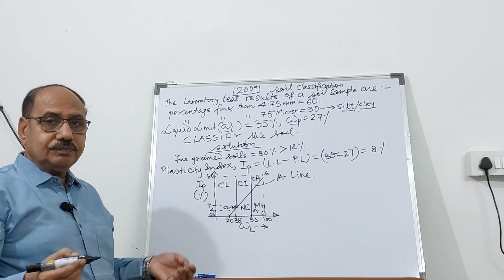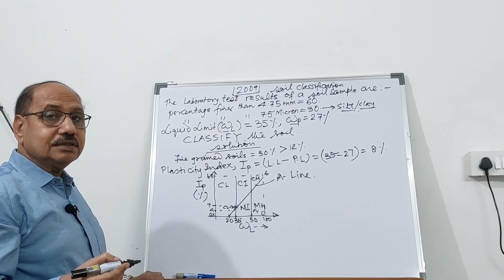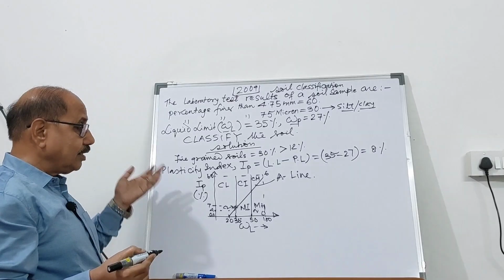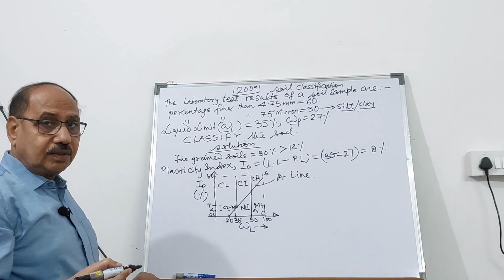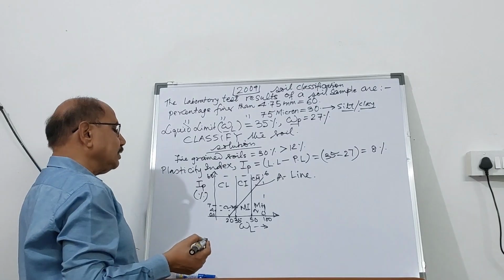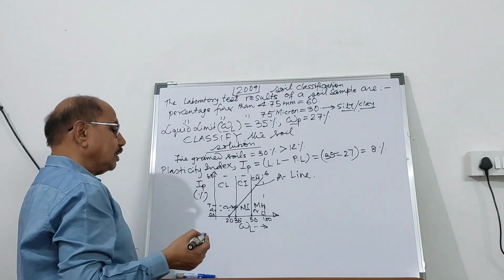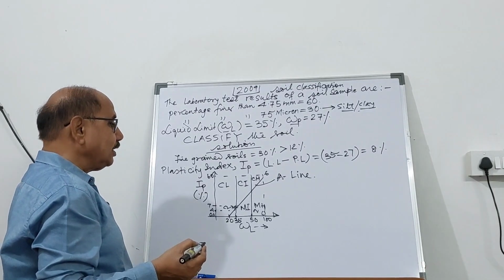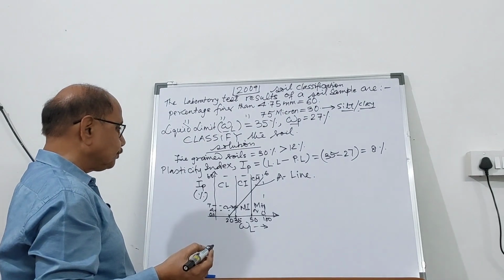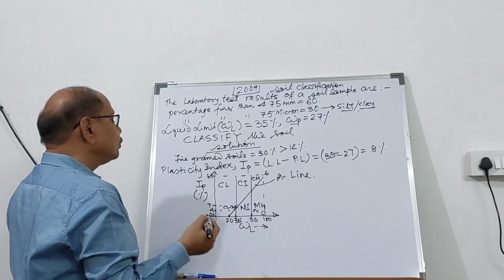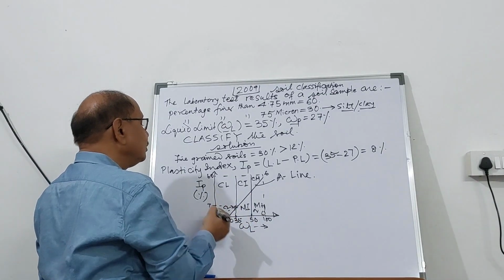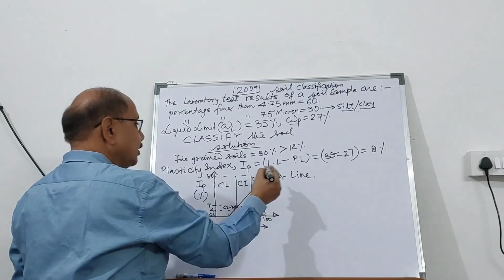For example, the soil which contains a mineral like montmorillonite is considered to be highly plastic. Black cotton soil, CH, is always very high. The liquid limit is going to be high, and plasticity index is also going to be high. On the lower side, here you can just find out the classification based on this.